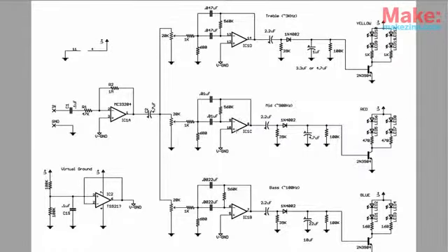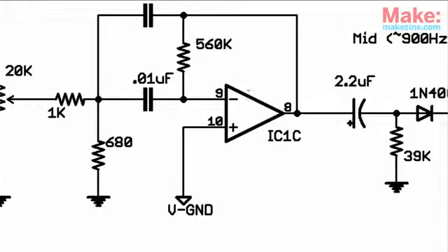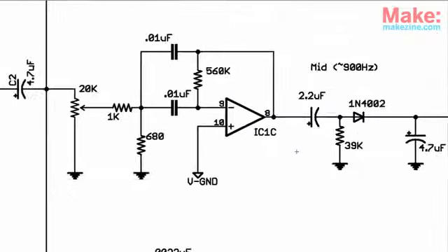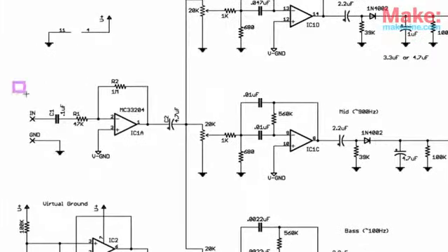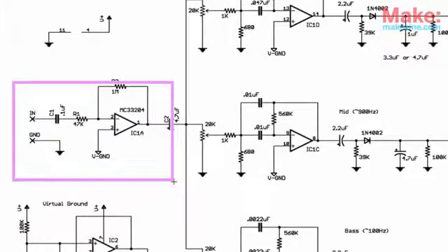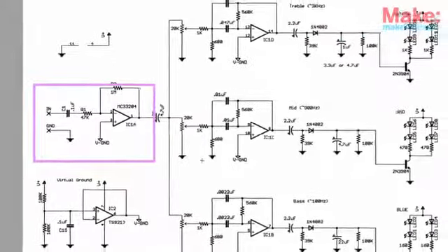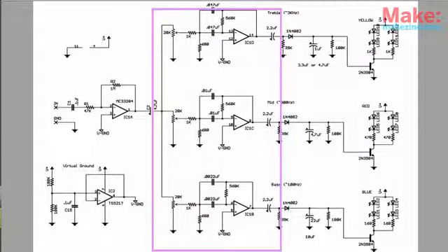At the heart of this project stands the multi-talented integrated circuit known as the operational amplifier. That's this guy right here, in case you're not familiar. An audio signal is connected to the first op-amp, which amplifies the signal for the circuit's second stage. From there, the boosted signal is connected to 3 op-amps, which are configured as bandpass filters.